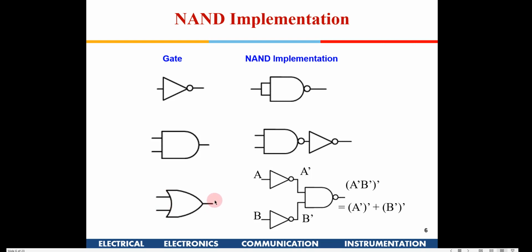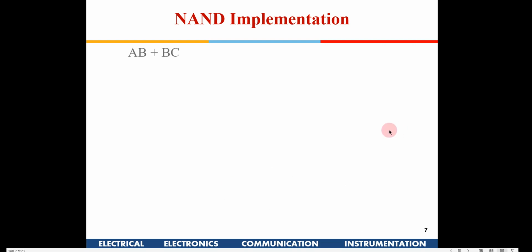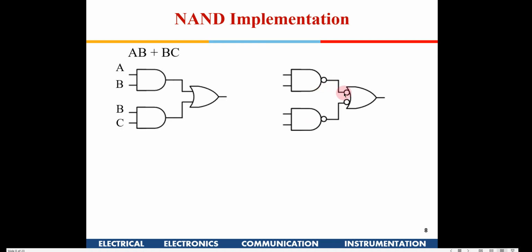That is NAND gate output only. If I put 1 0 or 0 1, the output will also be 1. And when I put 1 1 here, it will be 0 0 after the two inverters which I have put at the OR, and the output will become 0. So that becomes a NAND gate. That property we are using here: if you put two bubbles at the inputs of an OR gate, then this will become like a NAND gate.